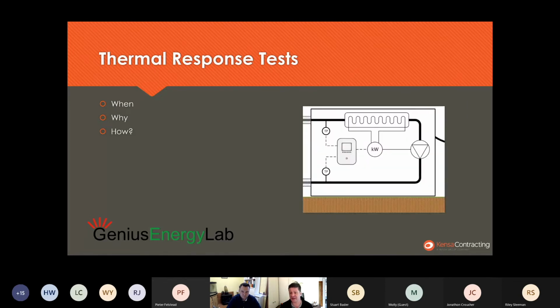We then turn the electric elements on, and these generally come on in stages, and we'll try and match the thermal input from that electrical heater to be approximately the same as the energy output we're expecting from a single borehole at that location. It's not critical, but it's good practice just to keep it about the same. We then run the test for 48 hours, and we get the data off the data recorder here back to the office where we process the results.